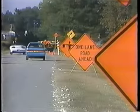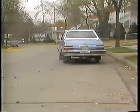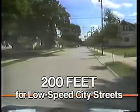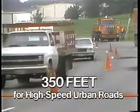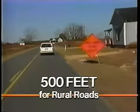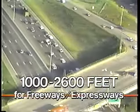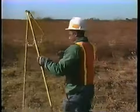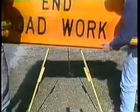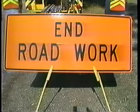In keeping with the Manual on Uniform Traffic Control Devices, a rule of thumb for the spacing between signs in a series is 200 feet for low-speed city streets, 350 feet for high-speed urban roads, 500 feet for rural roads, and 1,000 to 2,600 feet for freeways and expressways. Lightweight, yielding, or breakaway supports should be used for all sign installations. Sign installations should be reviewed to avoid any possible glare from vehicle headlights.